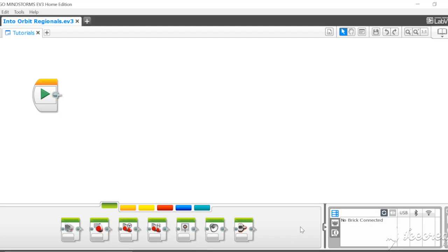Today we'll be going through the gyro and how to turn to an angle using it. The gyro is an excellent piece of equipment that tells the robot what angle it is currently facing, but it does have some limitations. One that you'll become accustomed to is drift. Drift is when the gyro thinks that it's still turning or changing angle, even if the robot stays perfectly still.